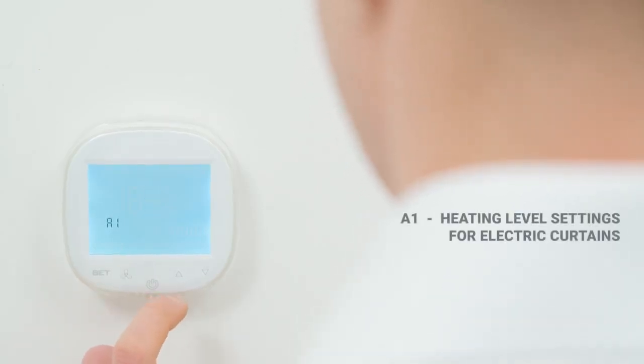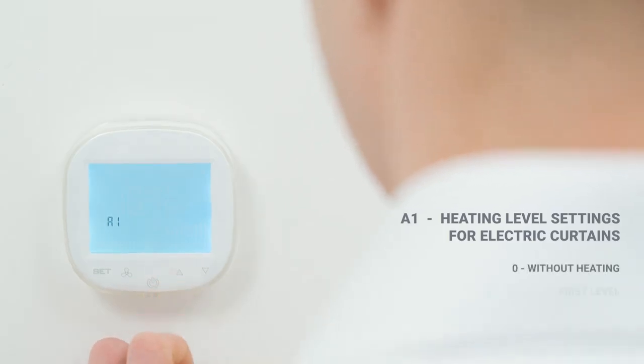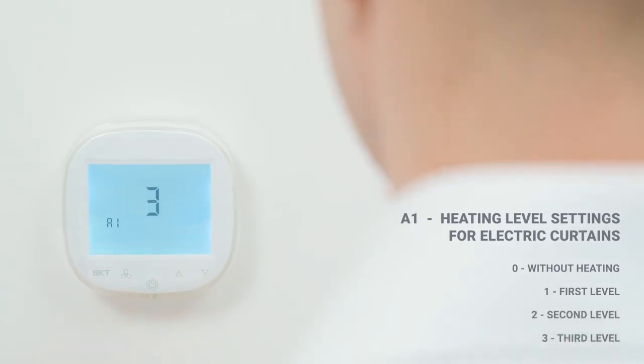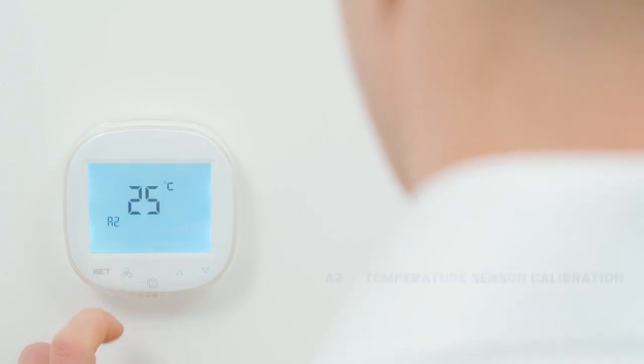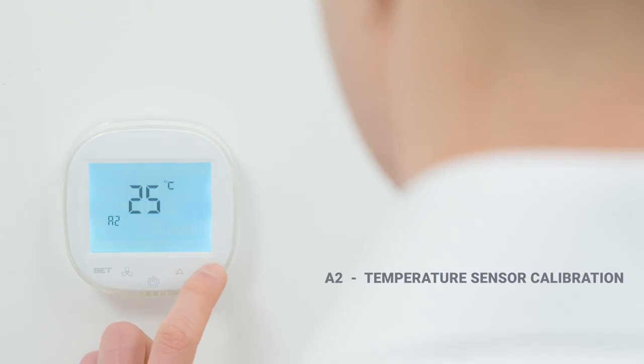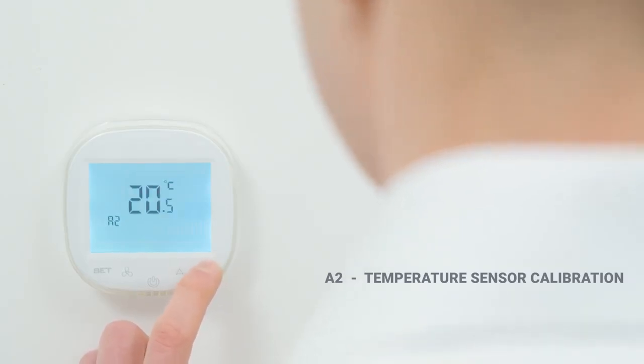Function A1: heating level settings for electric curtains. No heating, first, second and third heating levels accordingly. Function A2: temperature sensor calibration. If the actual room temperature differs from the one indicated by the controller, we can correct the sensor by plus and minus 8 Celsius degrees.